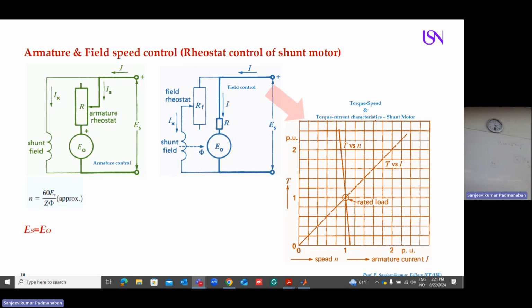Then as the speed increases and reaches the rated value, your torque is almost, not really zero. This is the ideal characteristic. It can be around 1 Newton meter or 2 Newton meter if the rated torque is 40 Newton meter. For example, I have a machine of 40 Newton meter, maybe 1 or 2 Newton meter is created because of its own rotating part. Because of the weight. The rotating part has its own weight. So this is the speed torque characteristic.